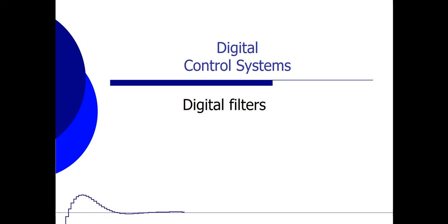Hi everyone. As you all know, PID type controllers are nothing more and nothing less than digital filters, which can be discretized, for instance, by using the backwards difference approximation or by using the Tustin discretization method. Well, this video does not discuss the different ways how to discretize a filter, but how it can be implemented after discretization has taken place, which has resulted in a discrete transfer function or in a difference equation.